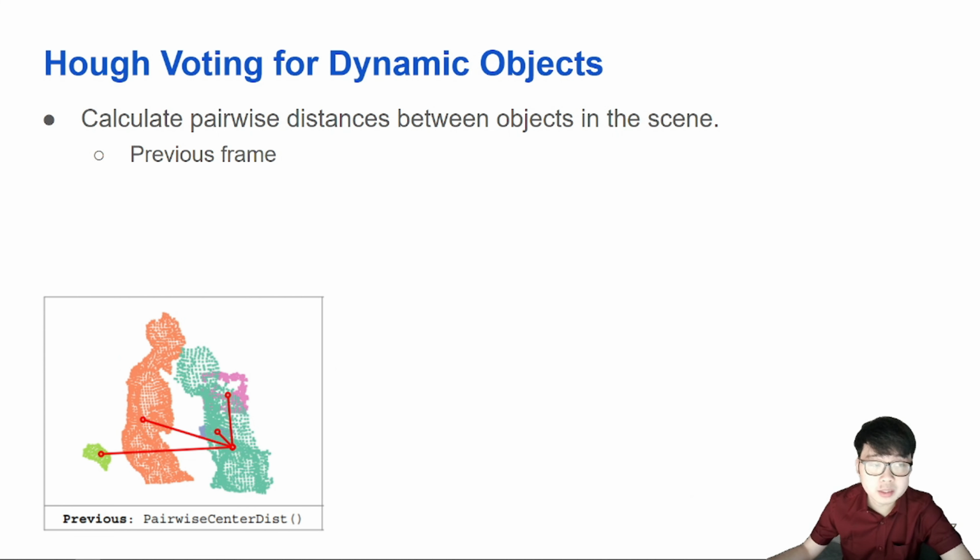To tackle this problem efficiently, we propose a voting mechanism based on geometry voting for dynamic objects. First of all, we segment the objects represented in the scenes and project them into depth maps, and then compute the pairwise distances between the bounding boxes of the objects.